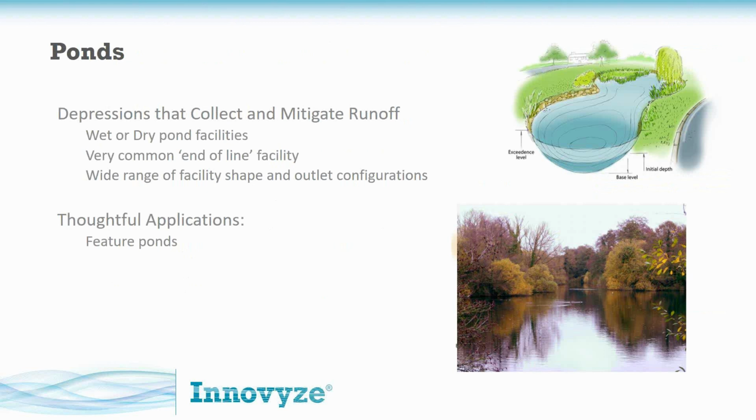Applications, well, a feature pond. If you have some sort of development of any kind, having a pond or perhaps a wildlife refuge is a really great focal point for your site. Another item would be, I mentioned, you can have maybe smaller ponds if they're dry, right? If you can have some filter, amend that facility with a filter zone and kind of anchor that sediment there, you're probably going to have a more effective, even just detention facility. You have a lot smaller footprint if it's dry, okay?